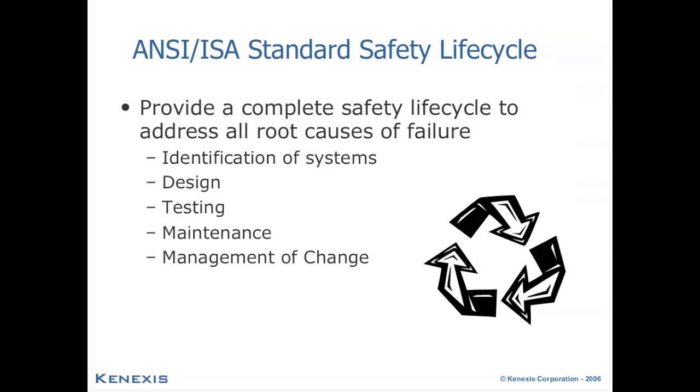The ANSI ISA standard S84 provides a safety life cycle that is intended, I think in broad measure, to address most, if not all, of these root causes or underlying causes of failures that we see in the accident data.